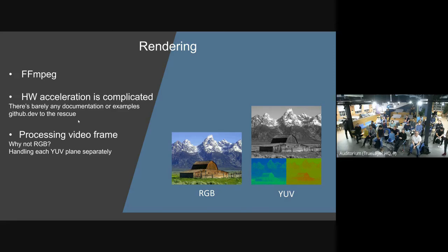And it's done that way to save space, basically, because the human eye is not as sensitive to color changes as it is to brightness changes. So if we can lose half of the information in the color, we can still perceive the full image as a very high quality one, because we just can't see those little differences in the color itself. We only look at the details in the sharpness of the brightness of the video.